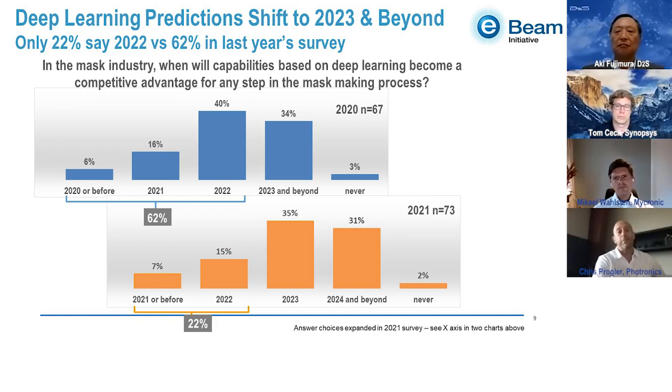I mean, the one classic place people have been trying to do this is defect classification, so-called ADC, automated defect classification. Still a huge problem. We still get defects, and we have technicians staring at every one of them on an inspection tool screen, deciding if it's important, not important, should we repair, where did it come from, is this from an etcher? It's highly manual, and ADC has been an area where this sort of technology could have a very big impact, but it proves to be quite difficult, actually, to implement.